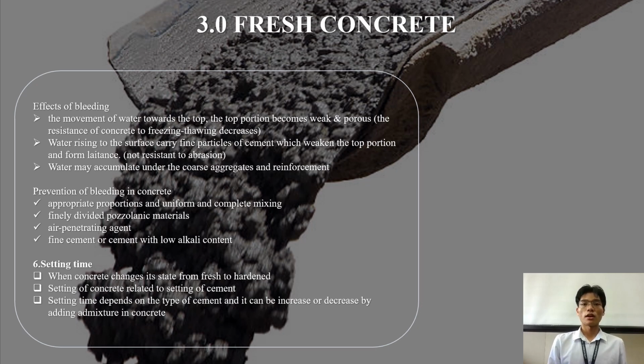Setting times. When concrete changes state from fresh to hardened, setting of concrete is related to setting of cement. Setting time depends on the type of cement and can be increased or decreased by adding admixture in concrete. Factors of setting time: mostly water cement ratio, suitable temperature, cement content, type of cement, and lastly, fineness of cement.